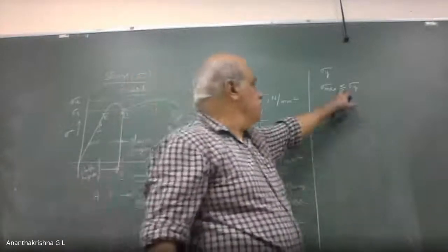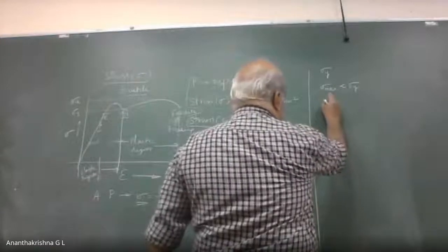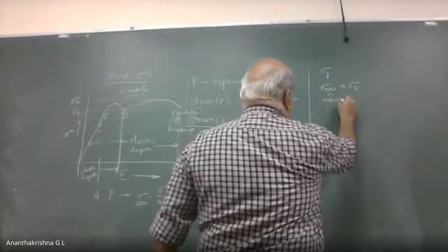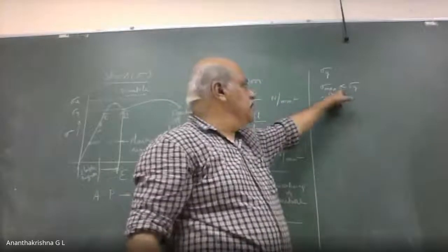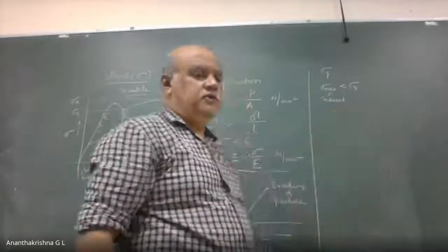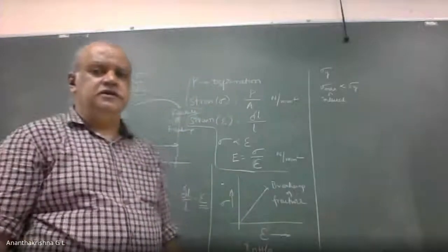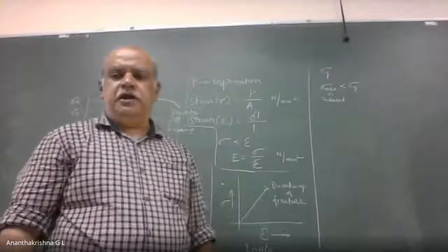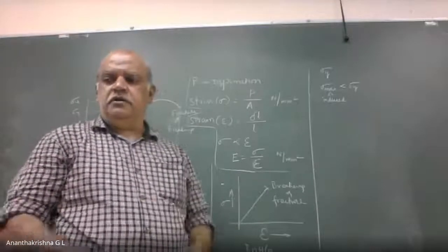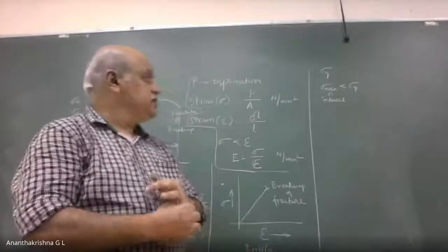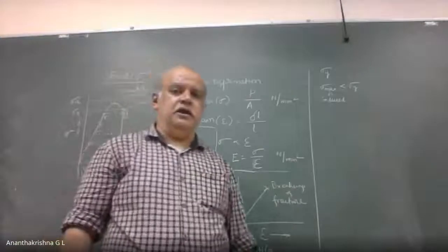Please note down. That is, sigma max, or sigma induced because of the applied load, should be less than the yield stress of the material. For ductile materials, yield stress should be taken as reference for designing the machine component.